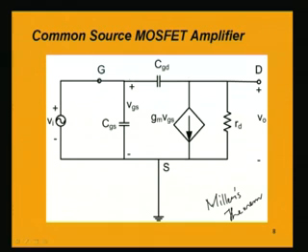Then we will not have a capacitance in between gate and drain, but we will be having capacitance in the input and output circuits, which can be combined with the capacitance which are already present. So, that can be done, and the analysis of this circuit will be following in a similar manner as we were earlier doing using Miller's theorem for BJT case.